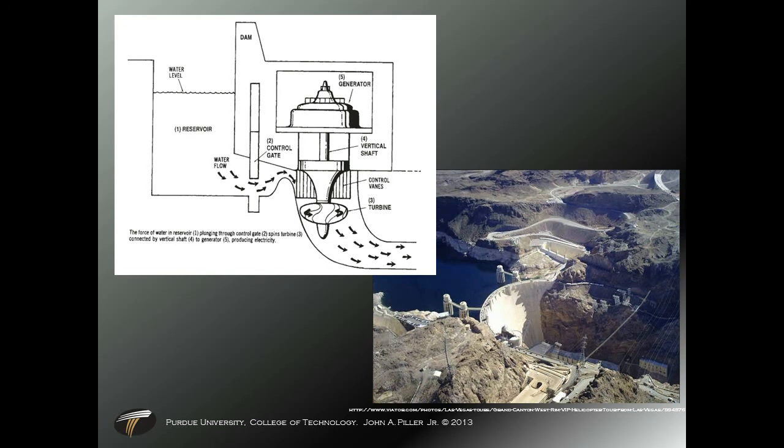We have the same issue with a hydro dam, but we don't have a governor. What we have is the capability of angling the adjustments of the blades of the turbine, and it's constantly angling those as water flows through to maintain the speed of the motor, to maintain the frequency.